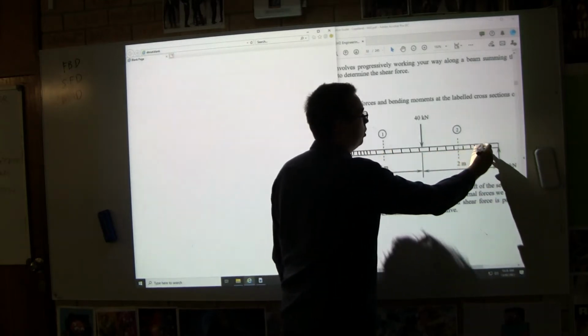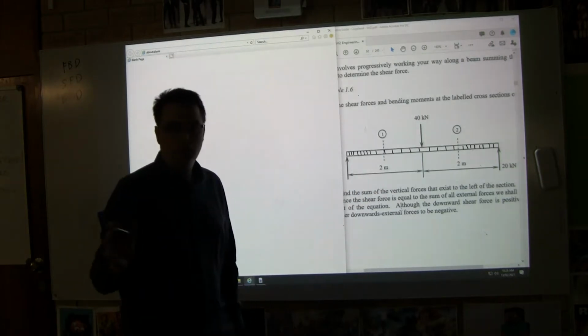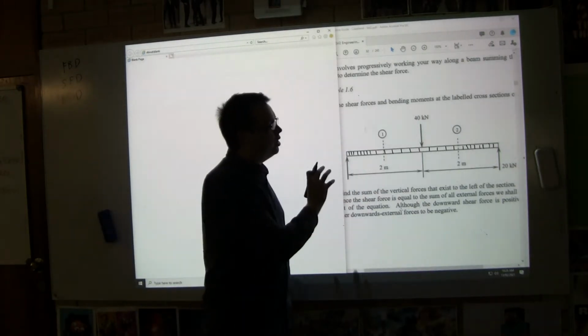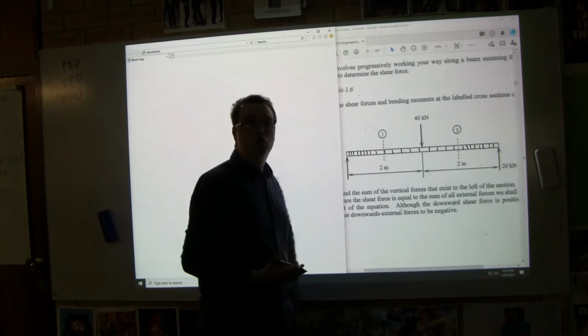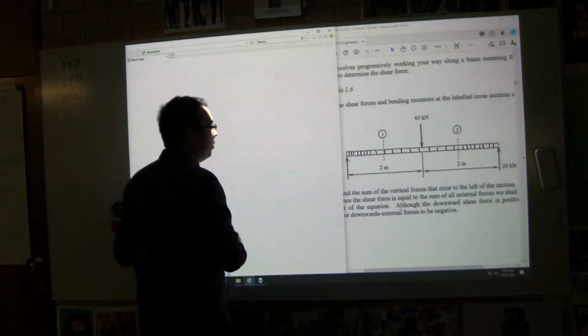Usually we need more on the columns. This is a bad example. This one needs an even shear force diagram. But the point is we can add more stirrups, more vertical pieces of steel, where we need more support for shear. Okay, so that's why we have shear.